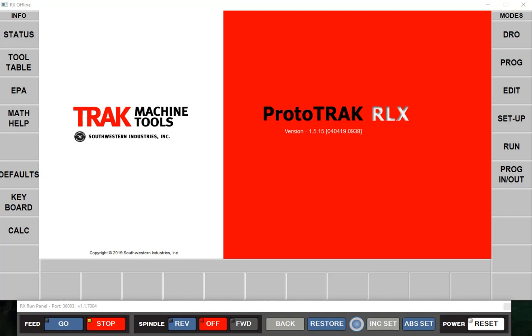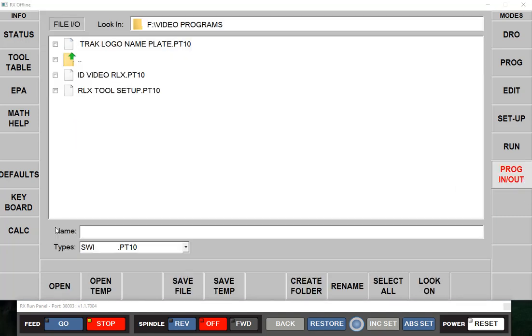Okay, this next scenario, I highly recommend that you do not use this. I think the best way to use the control at all times is to start out with a known tool that matches your library. So first thing you turn the machine on, go to DRO, pull up a library tool, set your 0. Now your part 0 and your library are all consistent and everything will work the way you're used to. However, there is a different scenario where I could actually open up a program